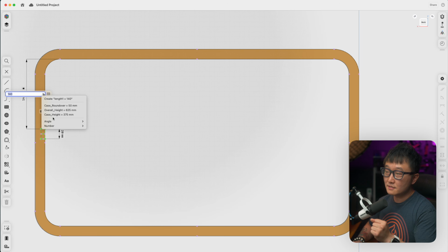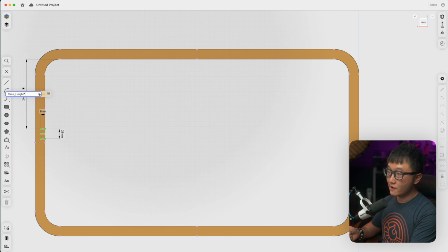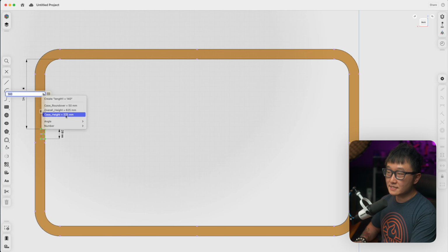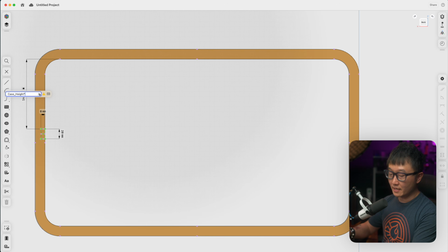So we're gonna use the case height multiplied by, actually exit this real quick. I need to make a measurement here. So this opening right now is 335 millimeters. So knowing that, let's go back here, and we're gonna use the case height multiplied by, let's see, 140 divided by 375 millimeters. Right now it's 37.3%. So let's just round that to 37%, which is 0.37.